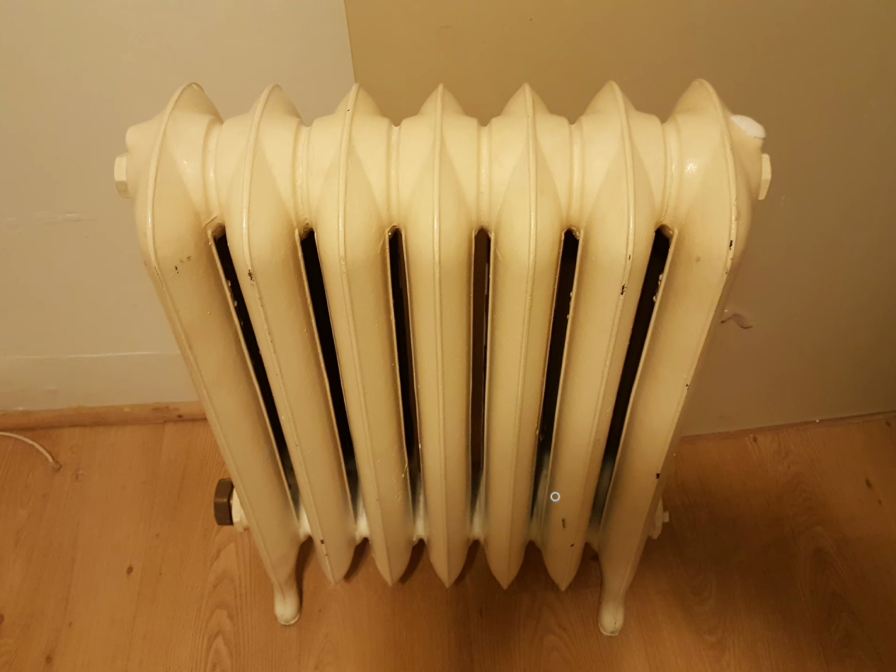But now you still have two-thirds or more, three-quarters of the radiator still filled with air. So what is the air vent going to do? The air vent's going to open back up, and it's going to start to vent out the air. There's still steam inside this portion of the radiator. This is typically going to be the first portion of the radiator that starts significantly heating up, along with this section right over here. Then it's going to start simultaneously making its way through the radiator. You'll probably notice the midsection is the last portion to heat up. The bottom is hot, the top is hot, but the midsection is the last to heat up, and that's based on the way those systems are set up with the style of boilers that they have.